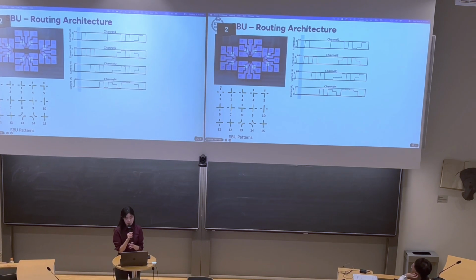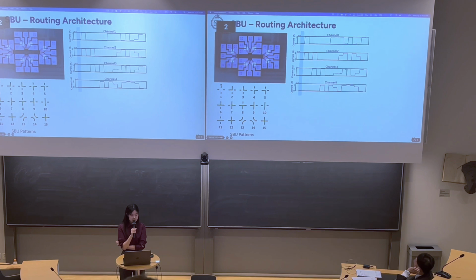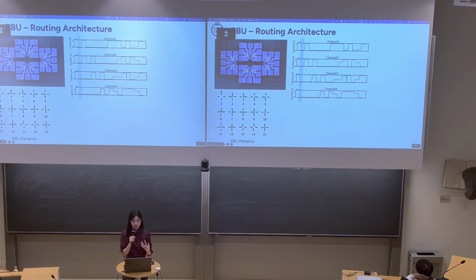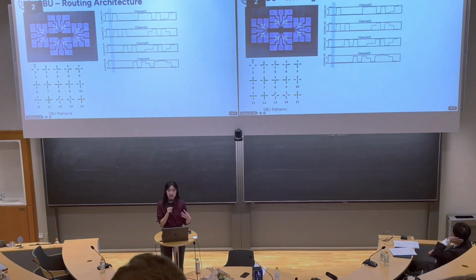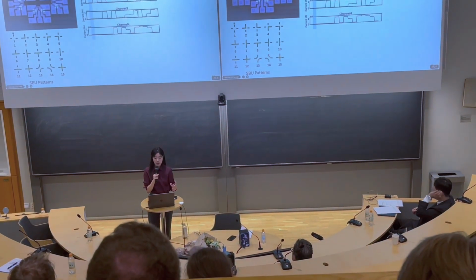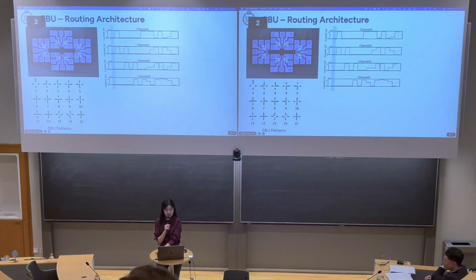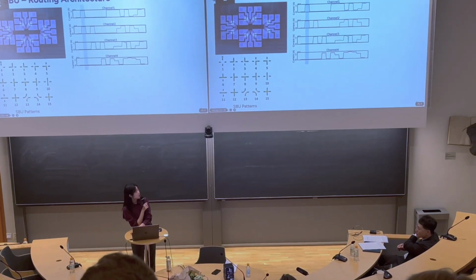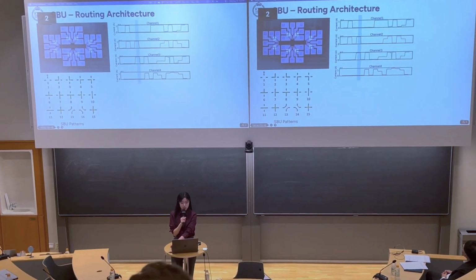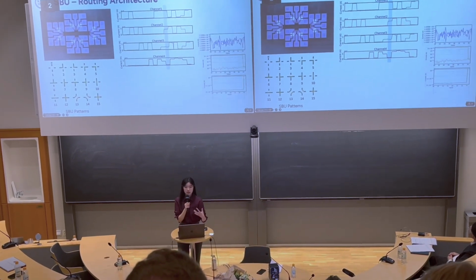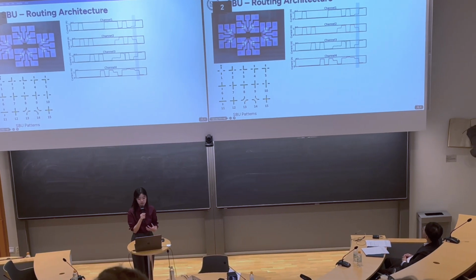And then on the same platform, we also implemented a switching box unit, and this is implemented by 4 interconnected 7-terminal NEM switches. And each of these switches can provide 2 signal channels. So for these switches, we can connect 2 of them together, these 2 or these 2, and we can also connect 3 of them together, and also we can connect all 4 channels.